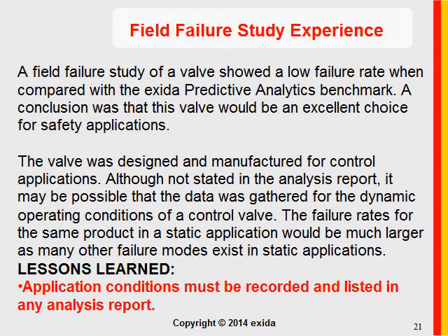However, again, looking at where the data came from, how was the data collected? The valve was originally designed for control applications. And even though the analysis report did not really state it, it was expected that the data that was gathered was all based on dynamic operating conditions of a control valve. The valve is continuously moving, whereas in safety, our main issue is the static application. That valve is sitting there open and it's not moving at all. Only when there's a demand from the process will we ask that valve to move.